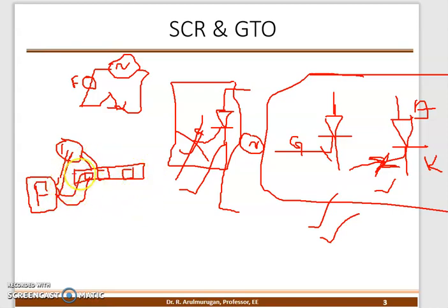If you have a switch, it means on and off. If I remove the switch from the plug point, then once I connect the wire, the fan is on. For example, let me tell you about the ceiling fan. How is the ceiling fan connected? Power supply to the switch, and switch to the fan, and the neutral is directly connected to the power supply. This is the method of connection of the ceiling fan.